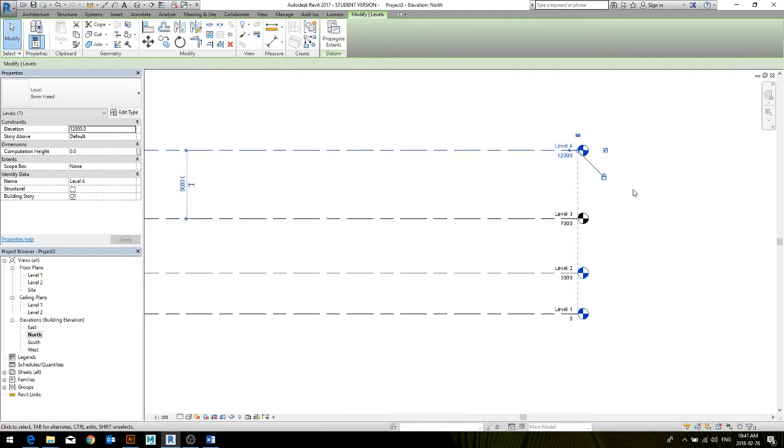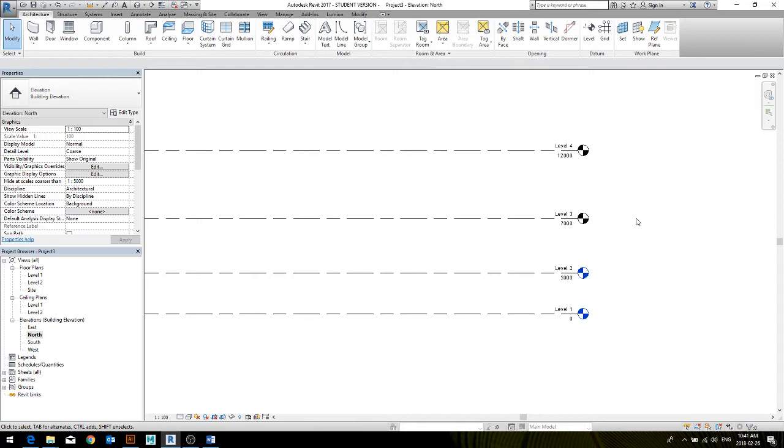The other thing that is very important is that, yes, when you have a two-story building, you have a level for the ground, you have a level for the second story, but in Revit, it also makes sense to have a level for under the ceiling, above the roof, or my maximum height, or below the foundation. As soon as you want to address something in an elevation and in a height, it's good to have a level defined for it.